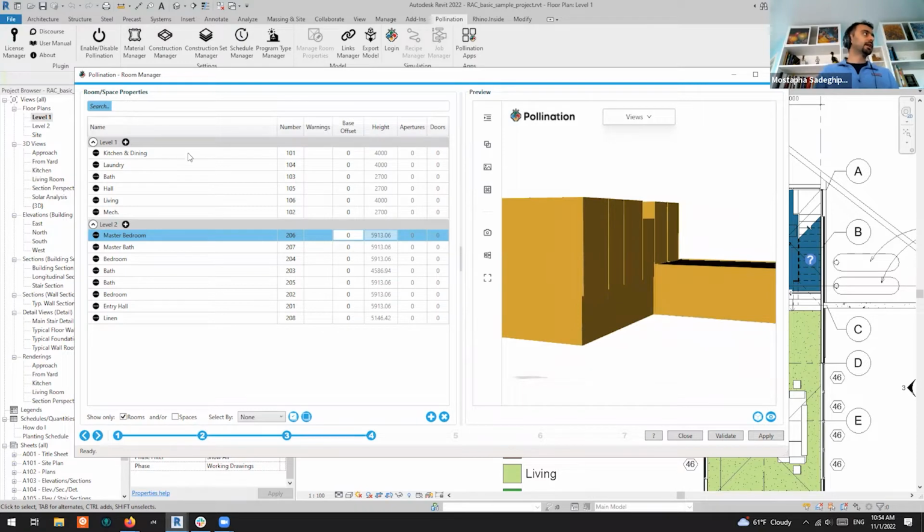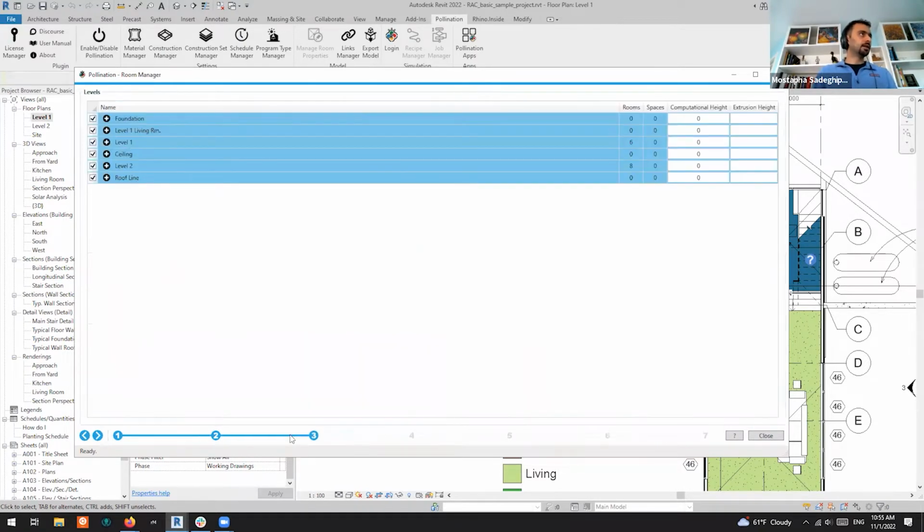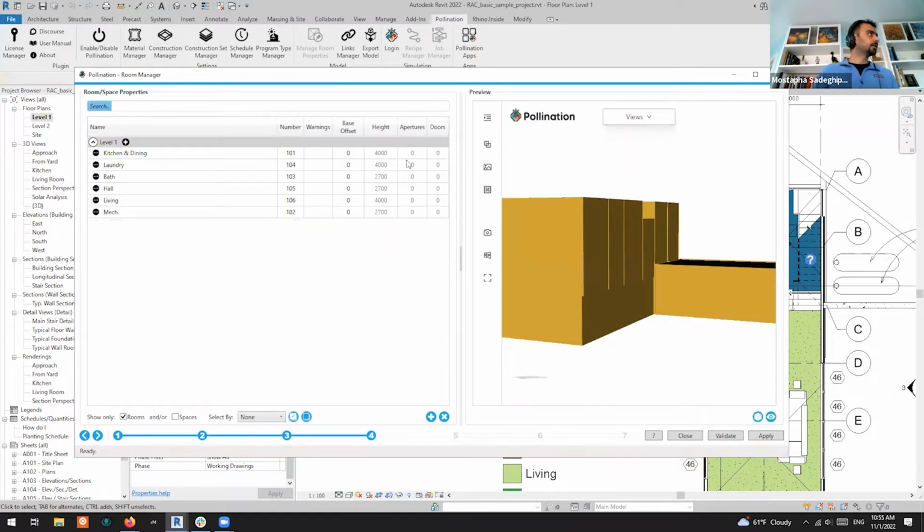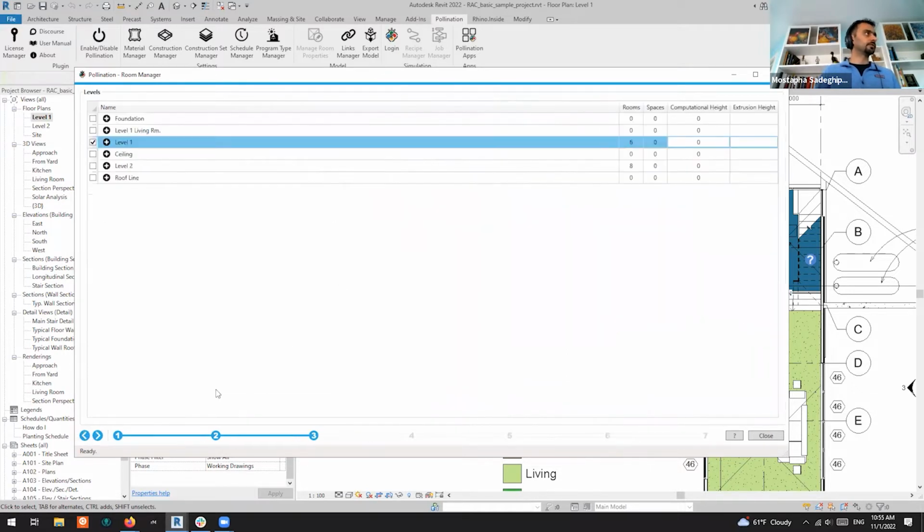These are the things that in 2D, in extruded mode, you can quickly fix. So you can go in levels and here force height. You can say whatever is on level 1, I want to have a certain height. What was the height again? So here level 1, let me set everything to be 4,000. So I go to level 1, I make it 4,000.